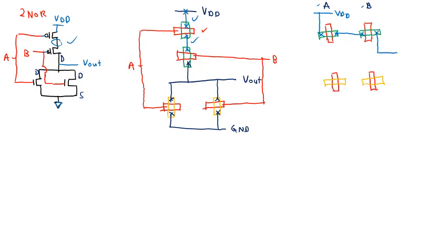And then the NMOS output should go to both the NMOS sides. So let's say you put it in the middle, then in the middle here, this is two connections, and this is the output. And then the ground is connected to both here. Then you write down like this, and this is the ground. Okay, so all connected. So this is the 2 NOR.